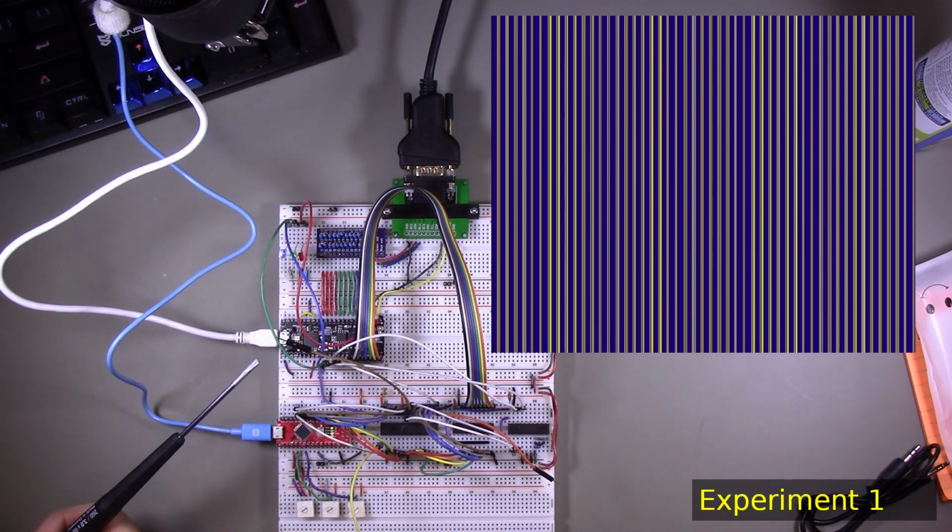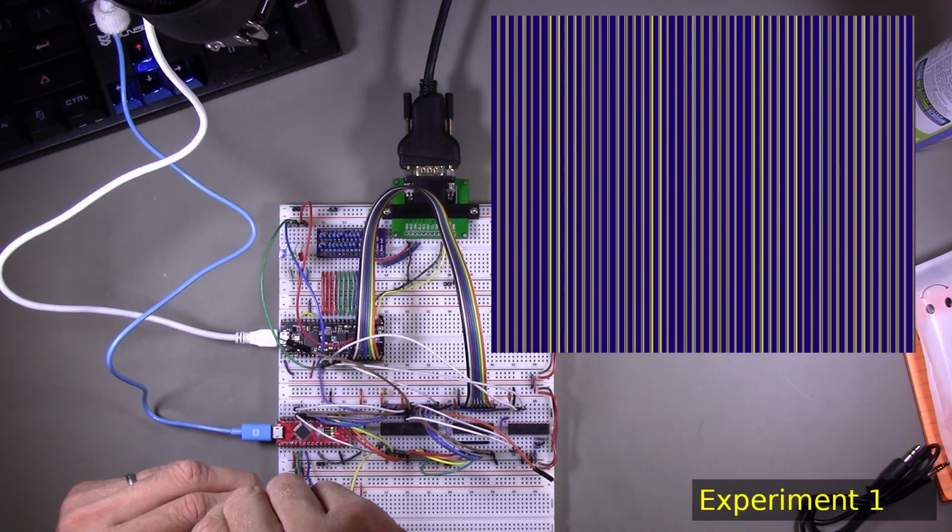But in a way, that was not a bad thing, because if we are going to use pipelining to do our computation and pixel generation, we only need to produce a pixel every clock cycle at 40 megahertz. And as long as that pixel is completely ready to go, then there's no problem doing it at 40 megahertz. So this basically forced me to really do pipelining.